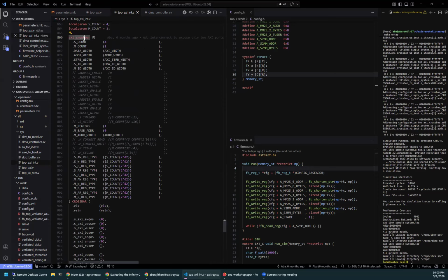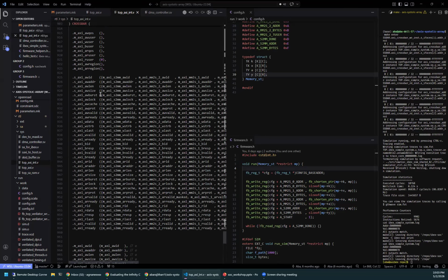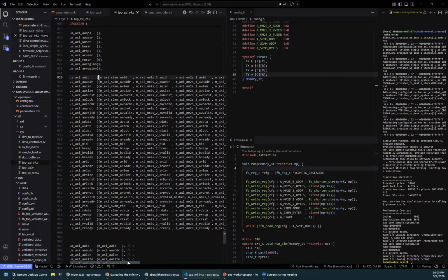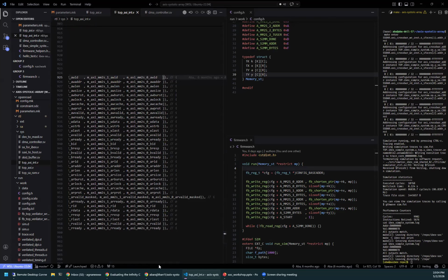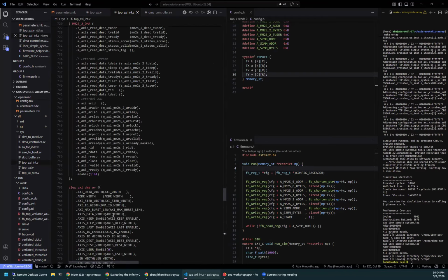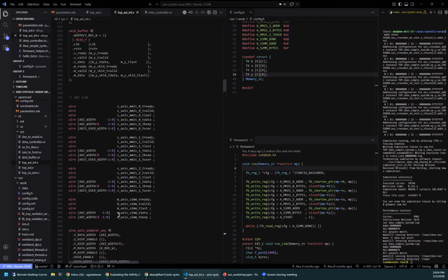So this AXI crossbar is the module from Alex Forencich, which is on the internet, right? So I'm saying I want 4 slaves here and 1 master here, and I set all these parameters in there, okay? And this is how the crossbar is designed to work. So basically you concatenate all your signals together into one big array, and you give it to the crossbar, and the crossbar will take that and work with that. Okay, right. So DMA write and DMA write and all.